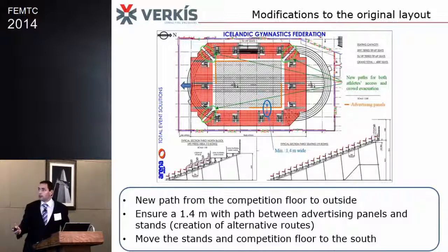I wanted people to be able to go out this way. They cannot cross completion 4 because there are some advertising panels, but I wanted them to be able to go down and this way. So I've created 3 passes that are 1.4 meters wide at these 3 ends directly in front of evacuation doors. And I had a 1.5 meter wide passage. A combination of these two gives me alternative routes, so people can evacuate easier, especially in case of panic. If someone falls, for example, in the stairway, people can still run this way.